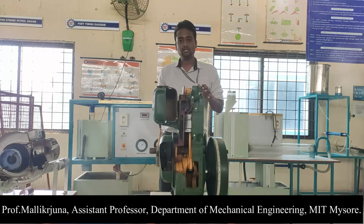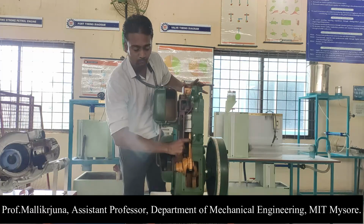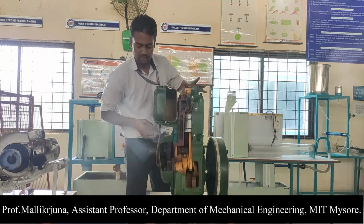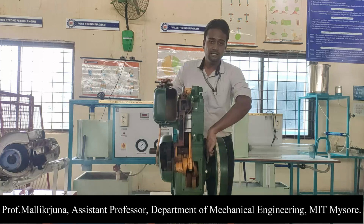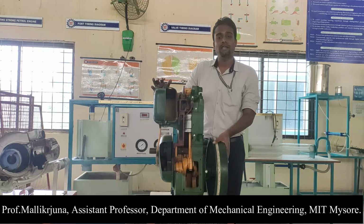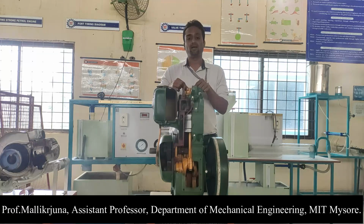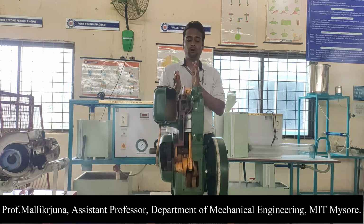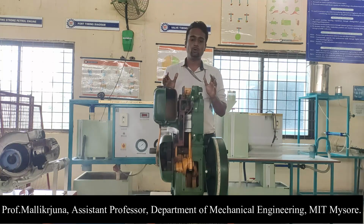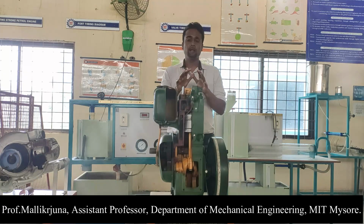Let us look at the various parts which are present over there. This is the piston, this is the cylinder portion, and this is the connecting rod, and these are the cam mechanisms which are present over here, and this is the crankshaft, and to the crankshaft we have attached a flywheel. So these are the various parts I will be looking into along with the valves. On the right side I have the inlet valve, on the left side I have the exhaust valve. Now my job is to look into the opening and closing of these two valves for various strokes. So that is my job now.